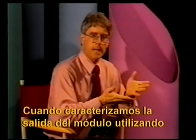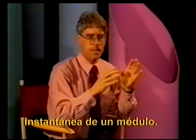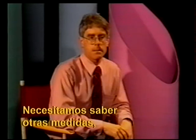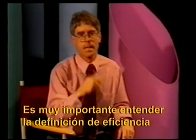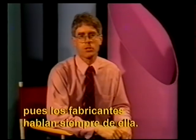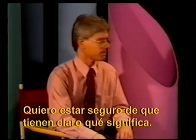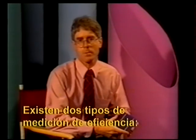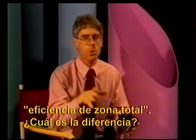When we characterize the module output using the IV curve, that's one description of the instantaneous output of a module. There's some other measures that we need to know, specifically dealing with efficiency. It's real important to understand the definition of efficiency and how it applies to solar modules, because all manufacturers and all sorts of folks involved in the industry refer to module or cell efficiency all the time. I want to make sure that you're clear on what it means. There's really two kinds of efficiency measurements that are made. One is called active area efficiency, and the other is called total area efficiency.